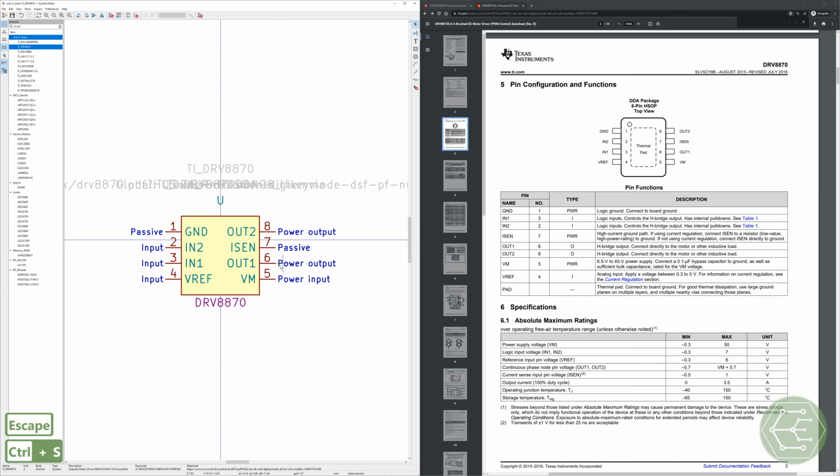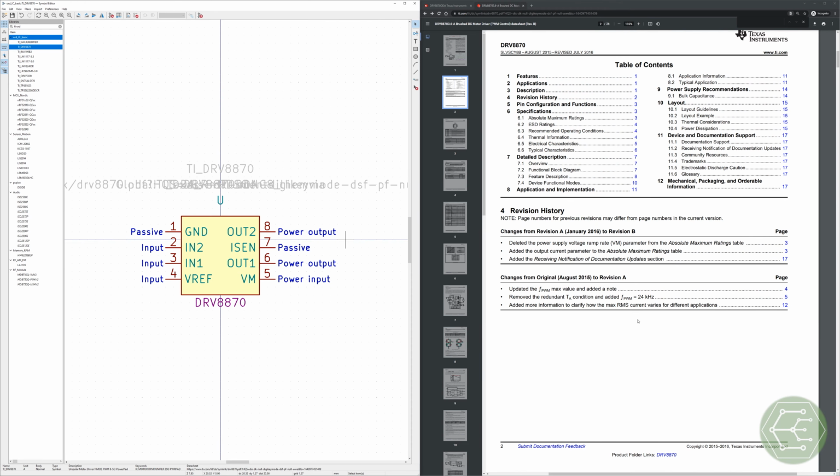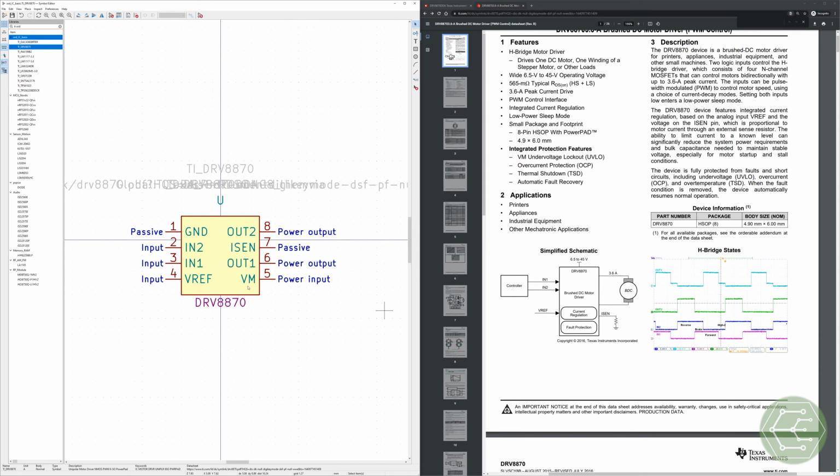And so here's what I like about this configuration. You can lay out your schematic and think about the physical implementation. Like if you pile a bunch of parts on this sense pin or a giant part, you have to remember that that's going to be in your way when you're laying out out 1 and out 2. That's going to be a problem. Likewise, a bunch of big capacitors on VM, you can think about, okay, well, maybe we'll put them over here, over there. And I like thinking about the system while it's being configured.